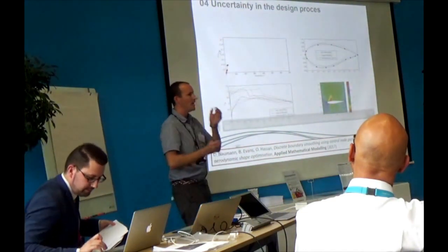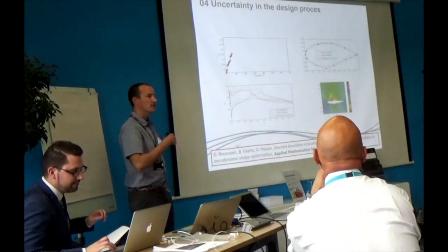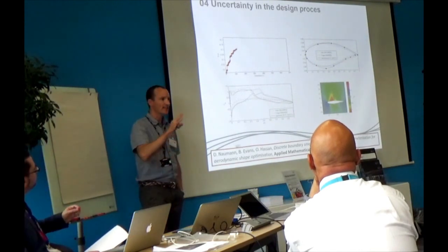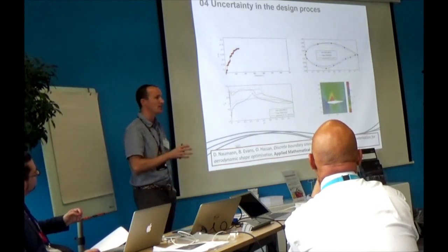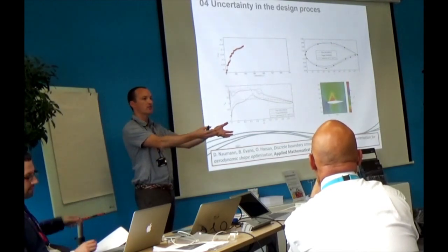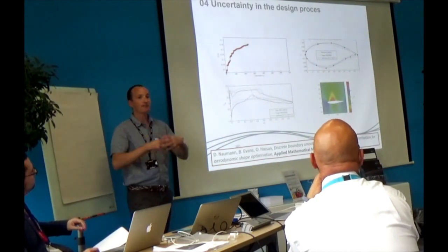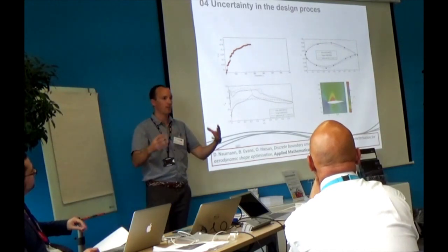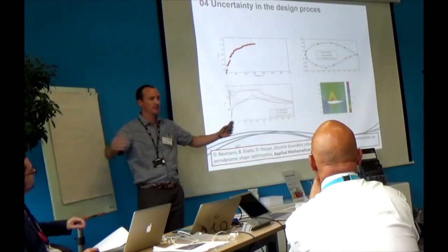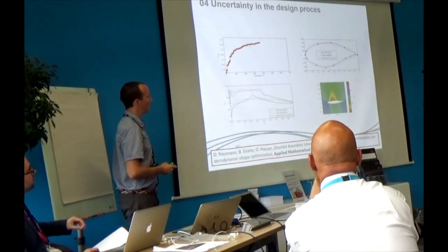So at around this time, 2 or 3 years ago, I had a PhD student who was working with me, looking at novel computational optimization methods. The kind of problems he was solving were relatively simple, 2D aerodynamic optimization problems like the inverse design of an aerofoil. You give a known pressure distribution over an aerofoil, can you find the geometry that gives you that pressure distribution? Using evolutionary methods, population-based optimization methods, where in each iteration of the design you're testing a family of designs, a population of designs, rather than a single design that's evolving, as you would in a gradient-based method.